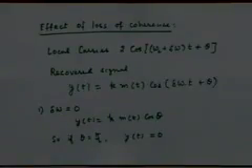There is no distortion in the recovered signal. The recovered signal is still proportional to m(t), but the problem may be that you don't have a recovered signal at all, particularly if your phase difference is as much as pi by 2, right? So you can see there is a perfect phase matching required, phase synchronization required. Is that clear?